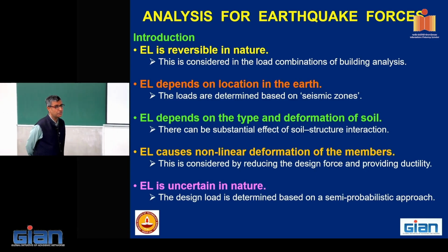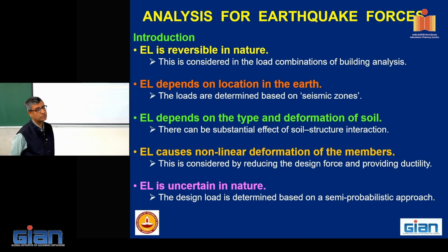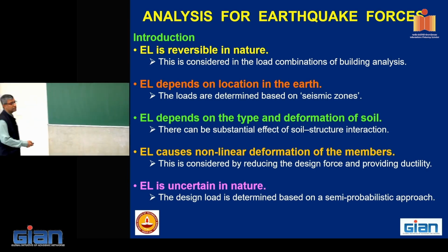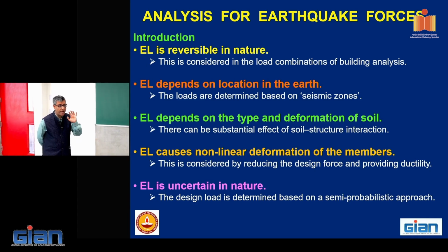Okay. Whereas when it comes to earthquake design, we are heavily involved with our geotechnical friends. With their data only, we have to start. I will tell you where it comes. And another very important difference with wind and earthquake is that typically we design wind to stay elastic.